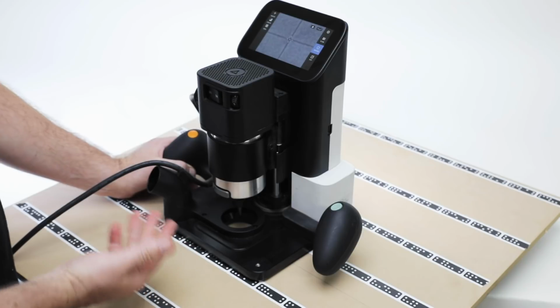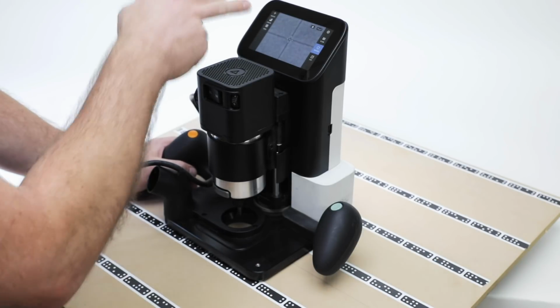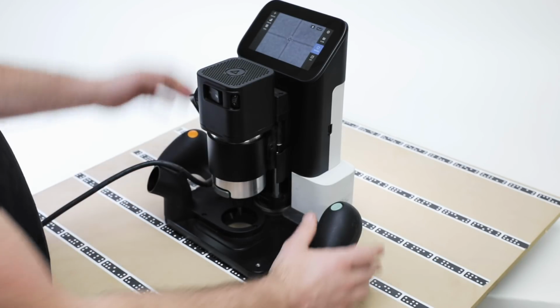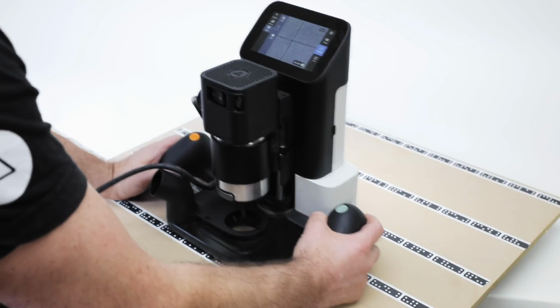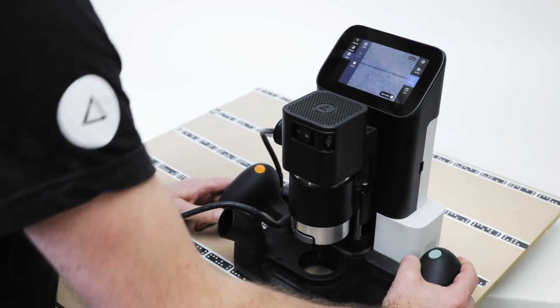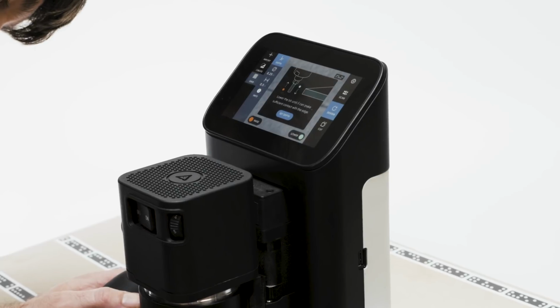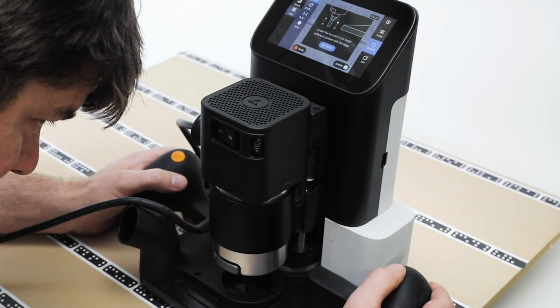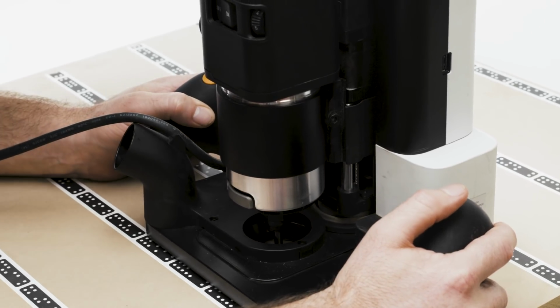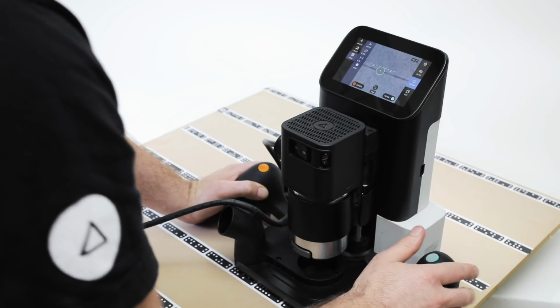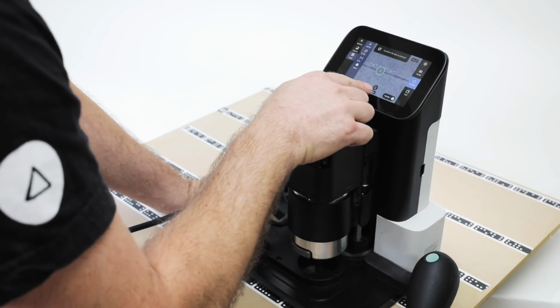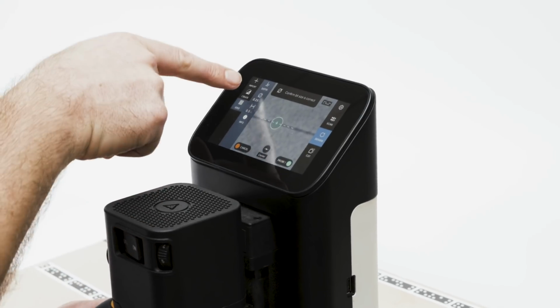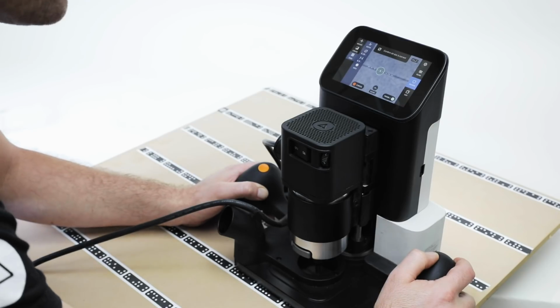I'm going to quickly find, on the screen I can see obviously my pencil mark. But to get it more accurate than what we see on the screen, instead of touching the probe against the edge, we're going to lower it down and observe it hovering right above that pencil mark. So I've lowered it. Once I'm happy with the height, I hit accept, and then I choose the center option. So I'm not probing the top of the engraver, using the point, which is the center of the cutter.